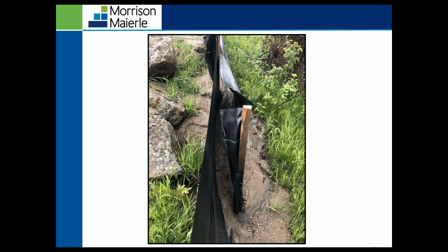So the first one right here is a silt fence. The BMP standards for this, when you reach the end of one silt fence and start another silt fence, is that you wrap the joints around each other, so then there's no gap in between the two different silt fences. So you can see right here, they weren't wrapped, they just overlap, just passing. So now there's a gap in between the two fences, which then is allowing sediment to go right around them and then discharging from the construction site.